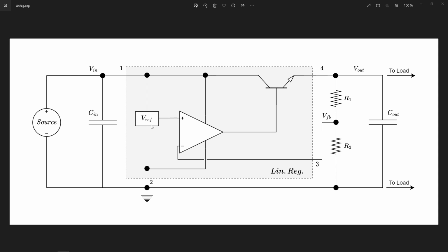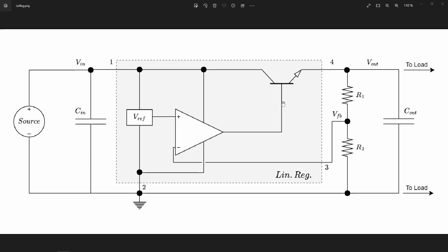Internally to the device, the way we convert, for example, our input voltage Vin to a lower output voltage Vout is via this contraption in the center within this light gray box. The very basic explanation is that we have a series pass element, which is typically a transistor. This might be a Darlington pair, it might be NPN, PNPs, or FETs, and we need according driving circuitry. And with that pass element, we are utilizing the properties of variable, essentially resistance of our pass element to alter how much heat and power we waste within that pass element, and thus we drop our output voltage by wasting power as heat. And that's as simple as it is.